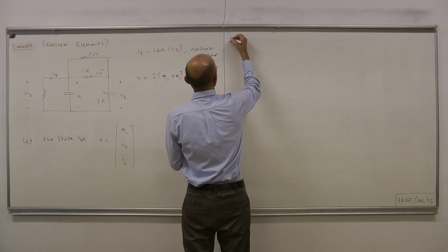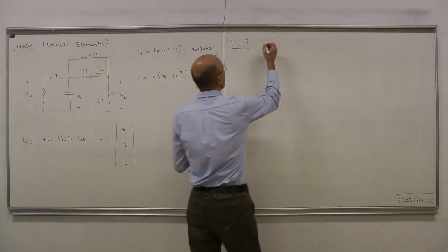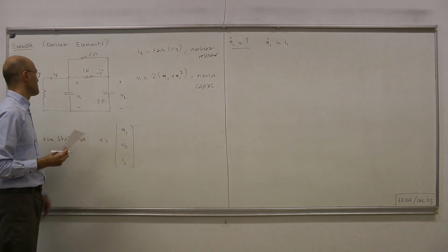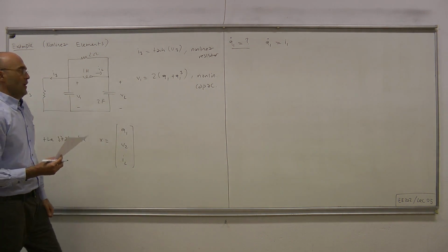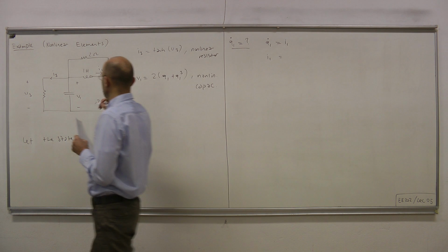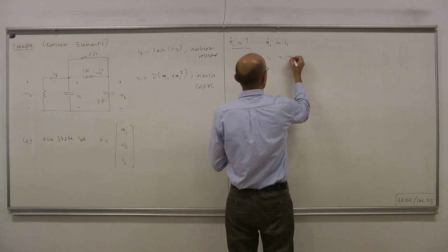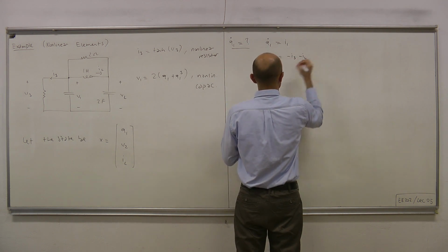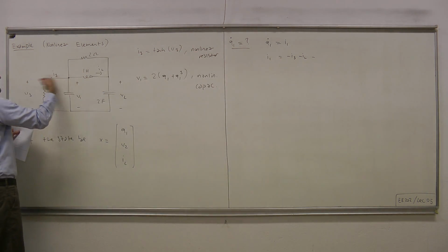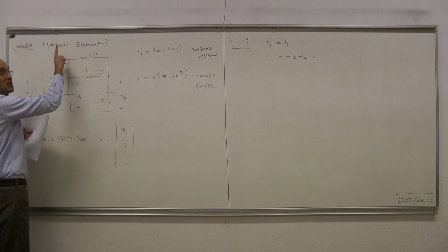Start with Q1 dot. By definition, Q1 dot equals the current passing through the capacitor. By writing KCL at this node, that current equals minus I3 minus IL minus this other current.